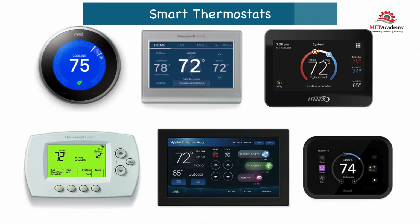Thermostat. Look for furnaces that have some form of communication with a smart thermostat to provide system information and alerts to system problems. There are also mobile apps that allow for notification and setting adjustments remotely, including routine maintenance alerts. The thermostat should allow for modulation of capacity. There will be a control wire access port for the thermostat wiring coming from the conditioned space.